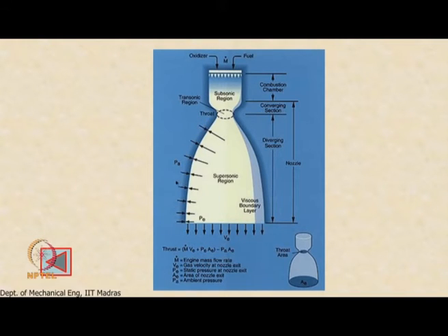You can see that the ambient pressure vector remains constant here. So, the net force is going to be this pressure minus the ambient pressure, and I do this throughout, which means that at every point here I need to measure my actual pressure with respect to the ambient pressure, in order to calculate the net force on the metal surface.